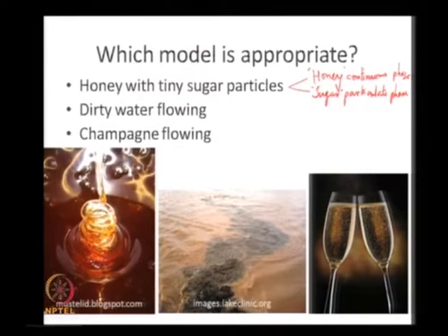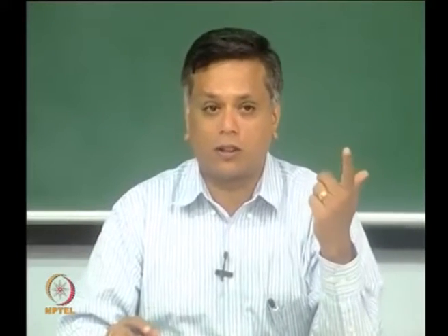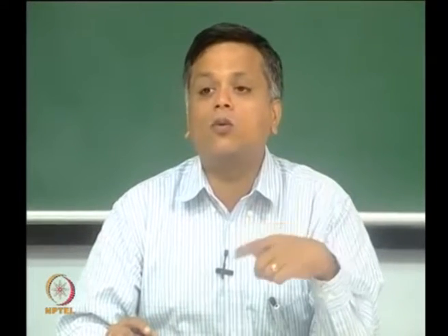Okay. So, in all these, of course, my exact model would work. The sugar is a bad example, but instead of sugar, if I had tiny bubbles embedded in this honey, then I essentially have little air bubbles in this honey that are moving with the honey as it flows. Okay. Now, that is a 2 fluid problem, and clearly the exact approach, which is my first modeling choice, would work for any 2 phase flow problem.